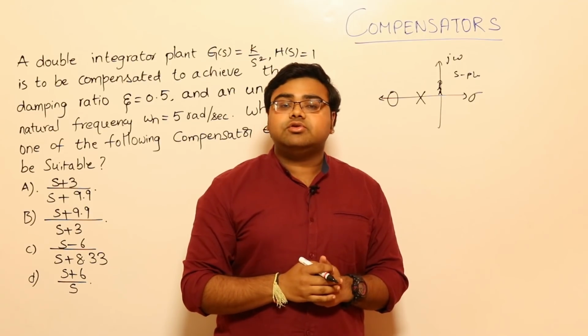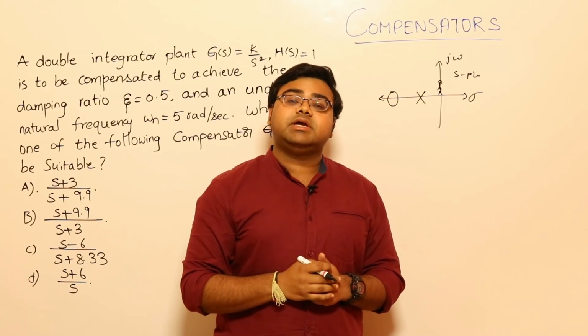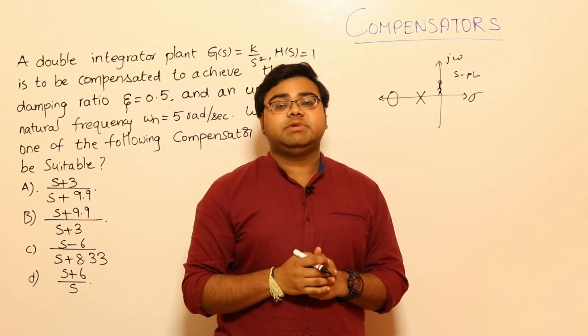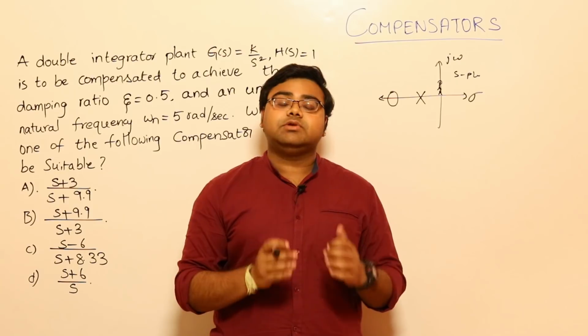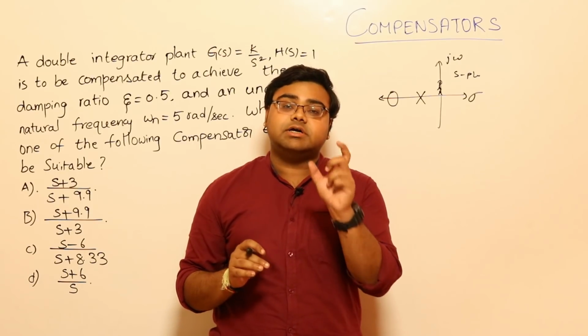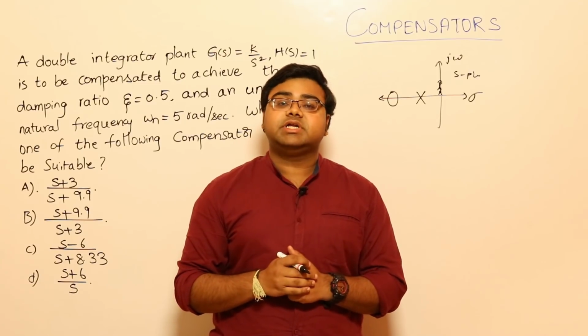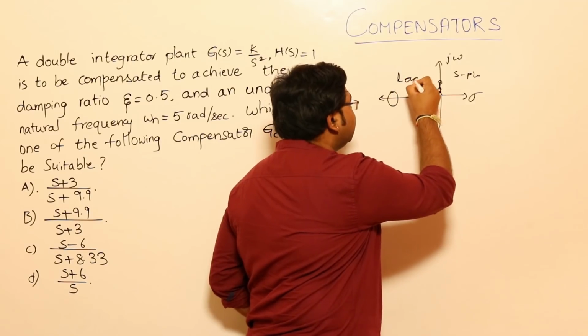Okay, now this is not good. You basically wanted to see a 0. So what is happening here? In English, you will make a statement telling that my 0 is lagging the pole, or my 0 is lagging. Whenever such a term comes, because of the 0 being lagged, you will say that that compensator is a lag compensator. So this is a lag compensator.